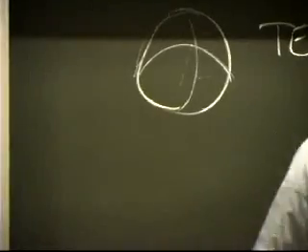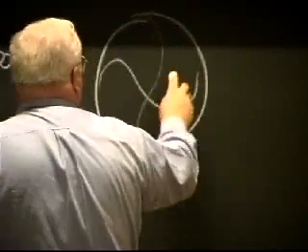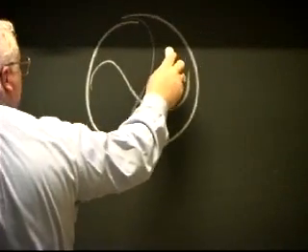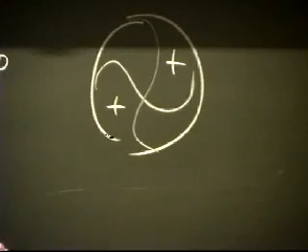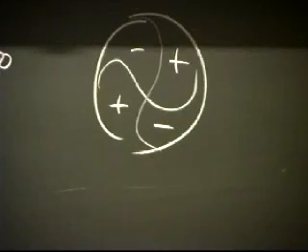If I had a full sine wave this way and a full sine wave this way, and I looked at my intensity, where the sine waves add, you'll get higher intensity, and where the sine waves are subtracting, one's plus and one's minus, they're interfering, you'll get a lower intensity. And so you'll get a speckled pattern when you get to multimode. So you could probably count across here and see how many wavelengths of the diffraction interference pattern you have across here. So now the other one is a deeper one.